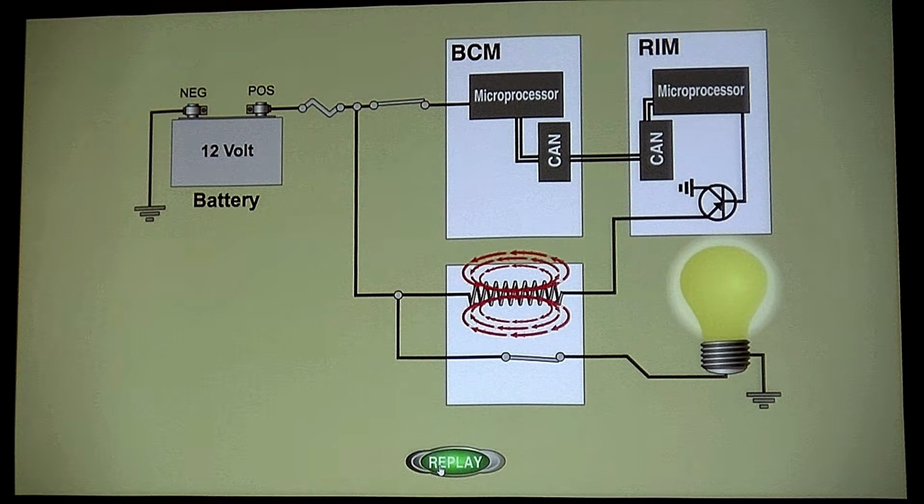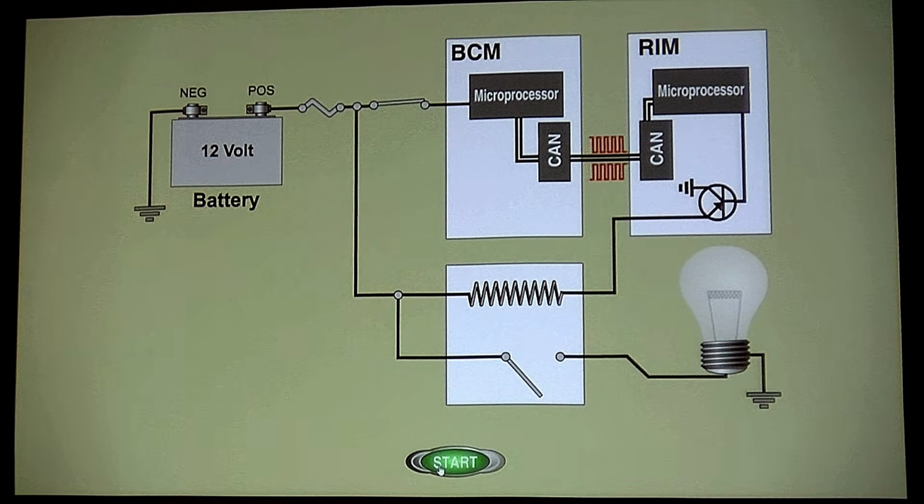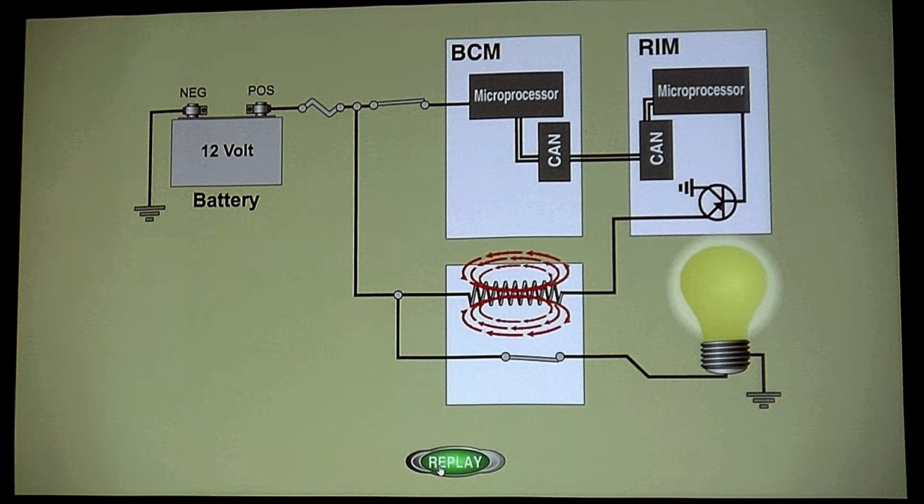So now when I put a switch on to have something applied, wipers, headlights, brake switches, whatever, these are only requests. So I send an actual request to a module. The module sends a message back to the rear, and now I turn on a current path with a different means. It's not a direct switch, right? This is directly controlled switching, not me switching it. So this is a whole different animal now, right?